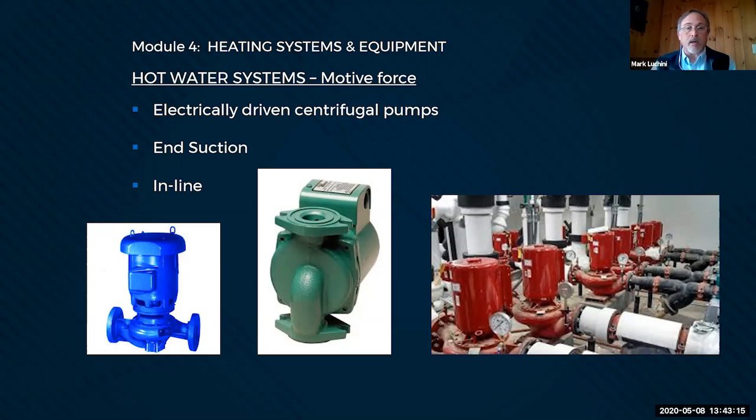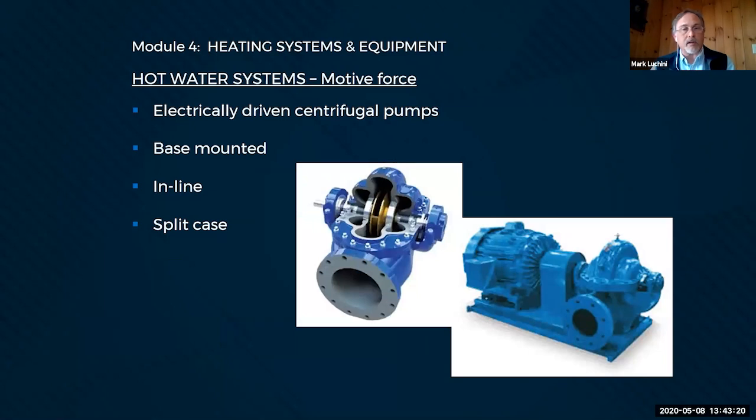Okay. Another type of pump that is a close cousin of the end suction is the split case pump. What they do there is they have a double-sided impeller. So instead of coming in one end, you basically bring the water in on either side of the impeller, these chambers here and here, and it gets sucked in both sides of the impeller and then spun around and spit out the discharge, which is, what's the word I'm looking for? Concentric. So the inlet and the discharge are on the same line.